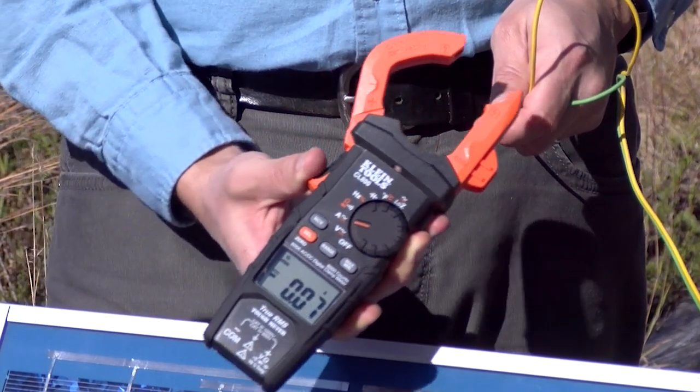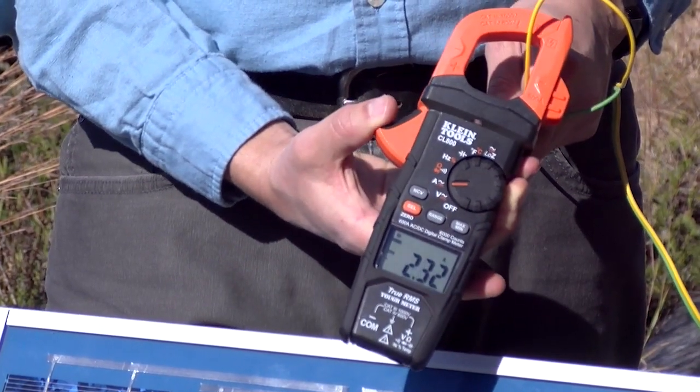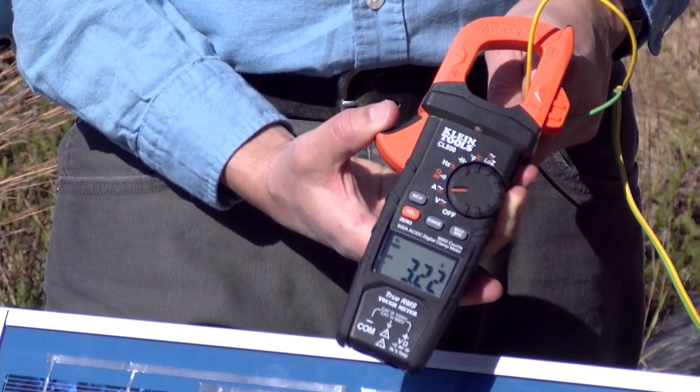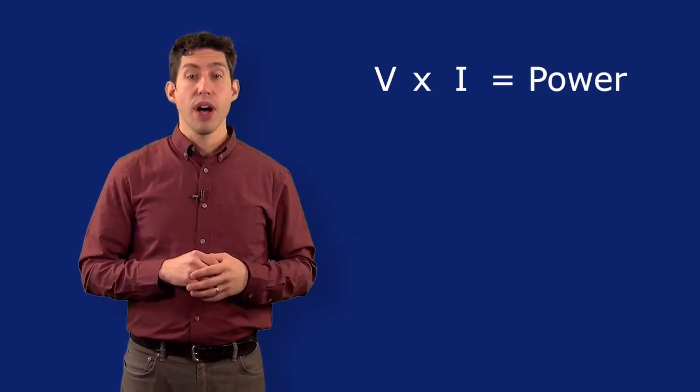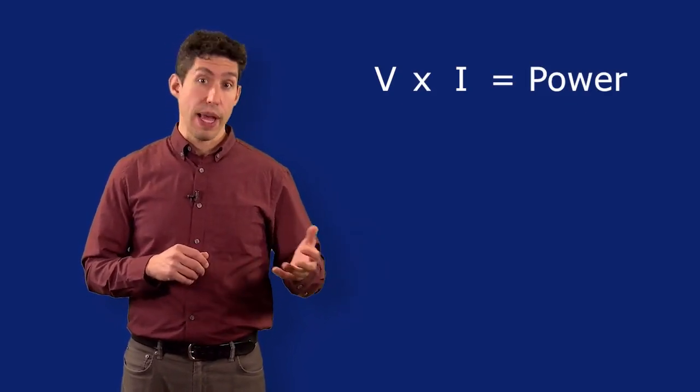So the other way to measure current is to use a clamp-on meter, which measures the electromagnetic field generated by moving electrons, and then just converts that value to a current. In practice, a clamp-on meter is almost always used since it's much safer and easier. Remembering that once we have the voltage and the current, we can multiply them together to get the power output of the individual module or the array.